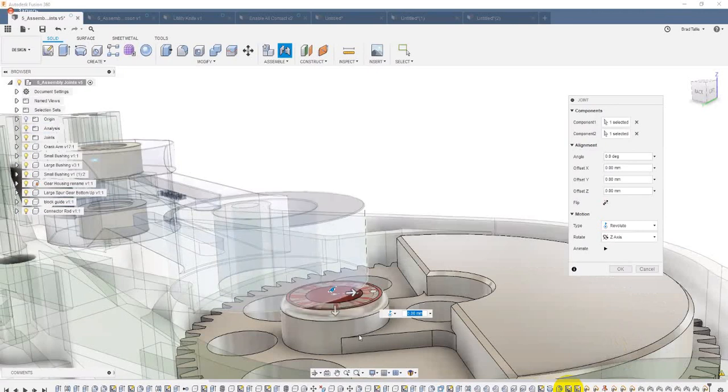Well, physically, you couldn't do this, right? It would cut into it. But what it's really complaining about is it says, hey, that red part needs to stay up here, so I can't go down there. But I want it to be able to revolve in here. So basically what I need is a revolute and a slider. That way it could slide up and down to get to the correct position.